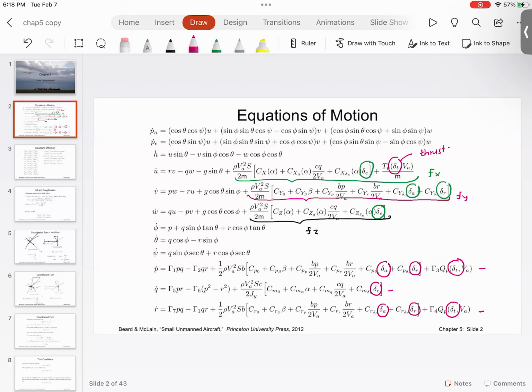Now, what is this disturbance? This disturbance is all this nonlinearity that is making this model super complex. But we will design our linear controller so that the linear controller is able to compensate for that small nonlinear disturbance. Everyone understood this? And that is the principle behind gain scheduling. So when we do the quadcopter control, we will notice that these techniques can be used.